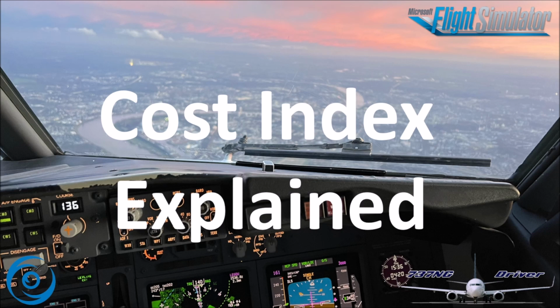So, resulting from the explanation or from the basic formula that we came up with earlier in this video, you will see that clearly a low cost index should be used when fuel costs are high compared to other operating costs, and vice versa. If fuel costs are low and your operating cost is really high, then you would fly with a very high cost index.